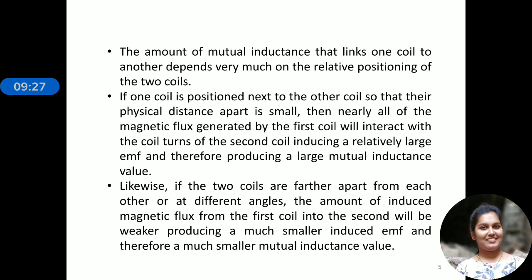So you have to keep in mind that the same coils will not always give us the same amount of mutual inductance, right? The same inductors placed at different positions will develop different mutual inductance. If you want more mutual inductance to be developed, place them together or side by side. If you want a lower value of mutual inductance, simply place them far from each other. Then the value of mutual inductance automatically drops.